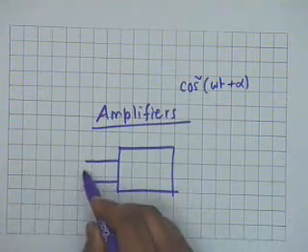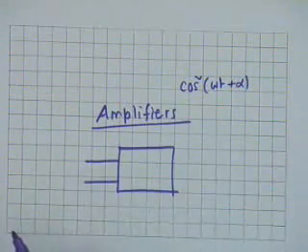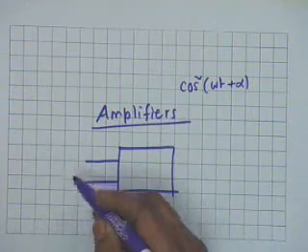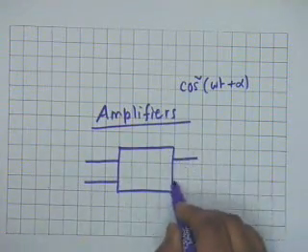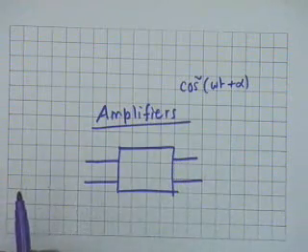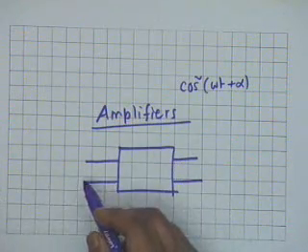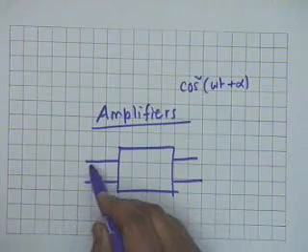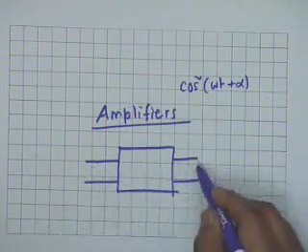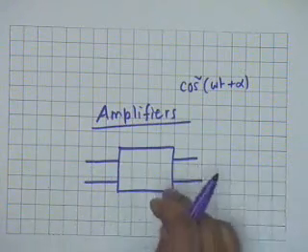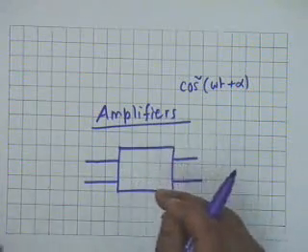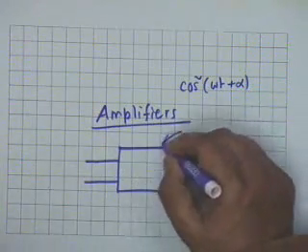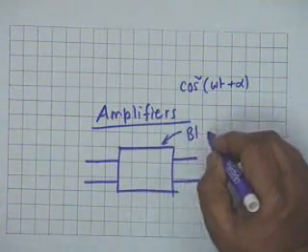That is, if I plug in a voltage source, what current flows, or if I plug in a current source, what voltage is developed. If it is a four-terminal network or a two-port, then what we are interested in is, if we plug in a source here, what is the response here. Alright, we don't want to look into what goes on inside. Then such a box in electronics is known as a black box.